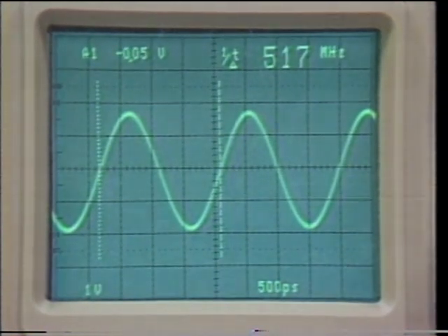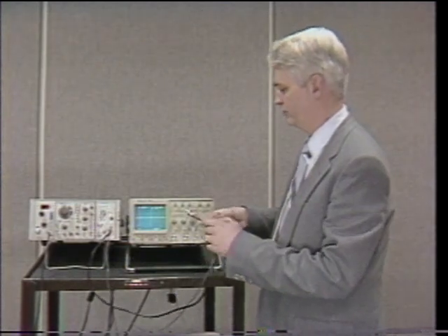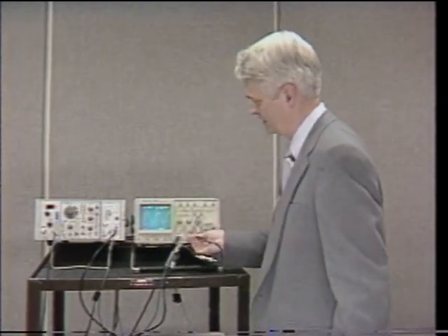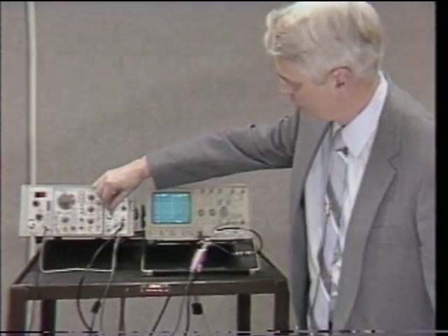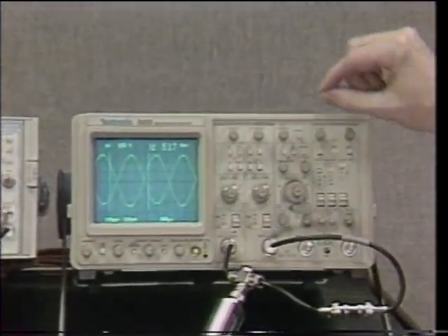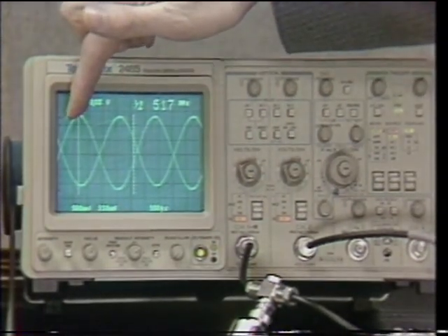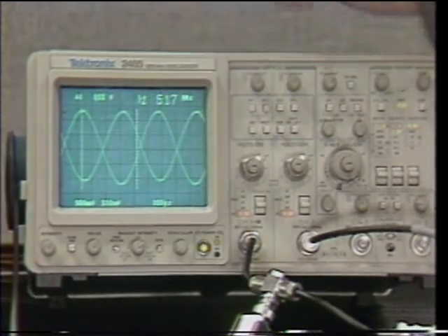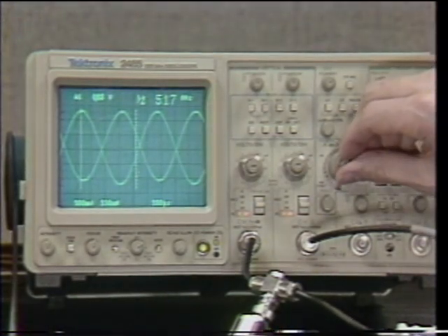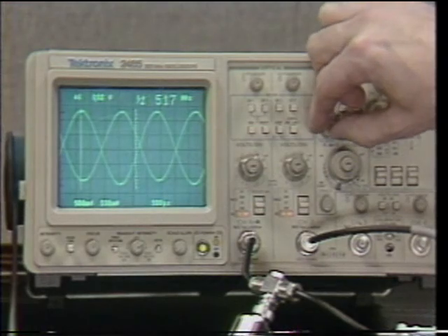Another measurement is phase. Now, to demonstrate that, we will apply our signal to channel 1 and channel 2 simultaneously. And we're going to have to lower the frequency slightly to get within the range of easy phase measurements and adjust our volts per division. Now, one of the requirements for measuring phase is that one cycle of the signal occupy exactly 5 divisions of the horizontal display. So to make that happen, we're going to have to adjust the variable. But the entire display moves, so let's start out by measuring the period of the signal.